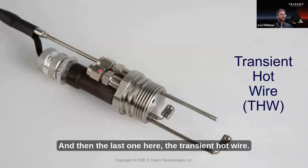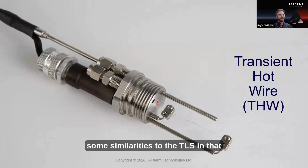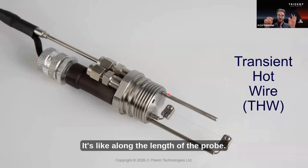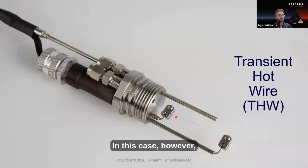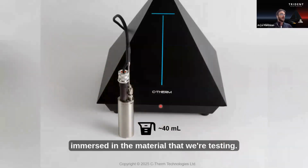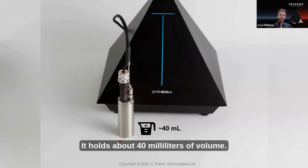And then the last one here, the transient hot wire. Looking at the hot wire, there are some similarities to the TLS in that the measurement isn't a flat kind of sensor. It's along the length of the probe. In this case, however, it's an exposed platinum wire that is immersed in the material that we're testing. Similar to the TLS, there's a standard cell that's provided. It holds about 40 milliliters of volume. And that hot wire really is geared towards liquids testing by and large.